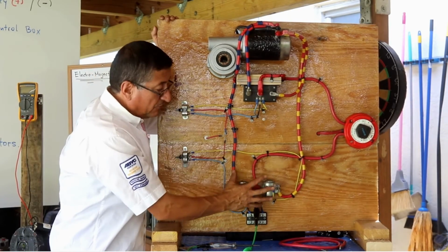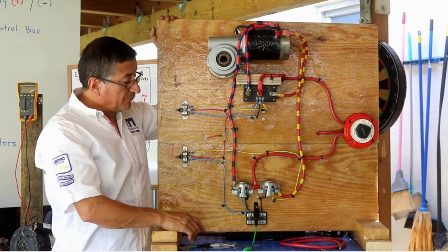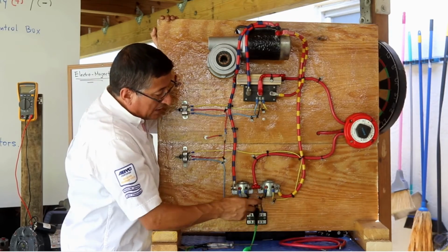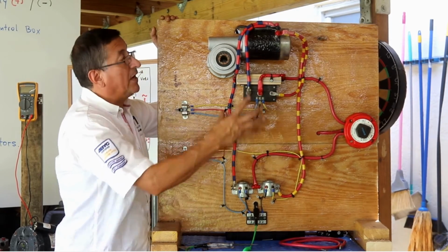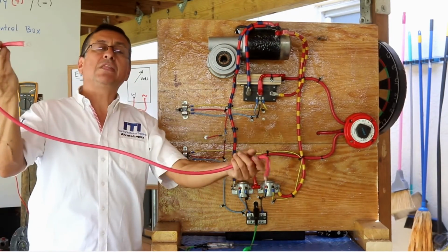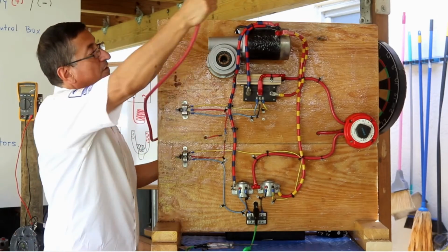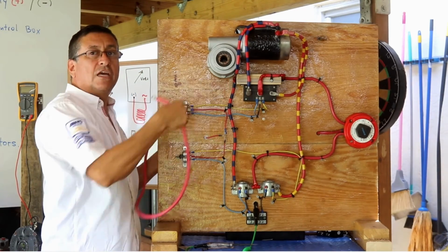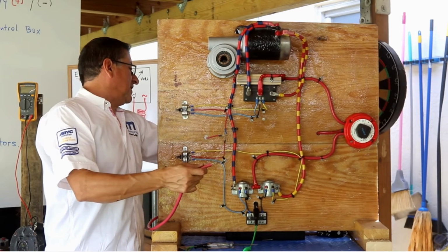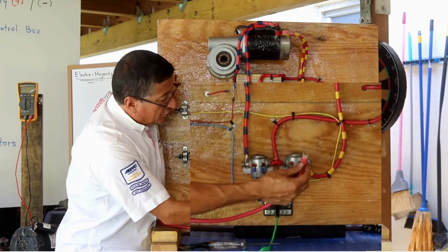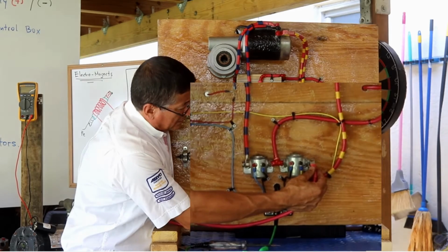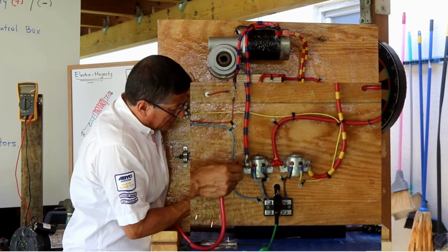The troubleshooting in this configuration is exactly the same. Suppose that the windlass is going down, the yellow one, but never up. You need to verify once again that the motor is good. How do you verify if the motor is okay? With a big cable, you bring positive directly from the battery and you check that the motor is spinning in both directions. And now you bring the power directly from the positive of the battery, and you check if the relays are okay. The outputs of the relays are okay, one direction and the other one.